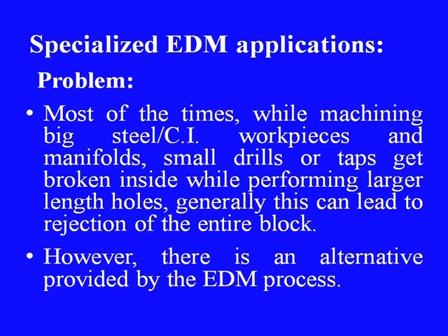Some problems are like this. Most of the time while machining big steel or cast iron workpieces and manifolds, small drills or taps get broken inside the hole while making longer holes, and generally this can lead to rejection of the entire block, which is a sheer wastage of money. However, there is an alternative provided by the EDM process in such cases.